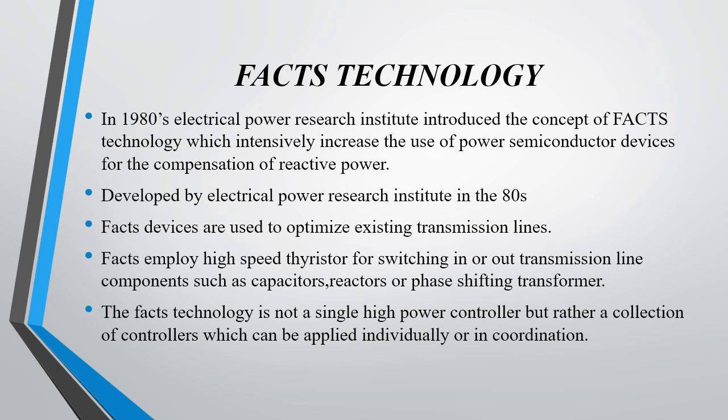Then let's move to FACTS technology. In the 1980s, the Electric Power Research Institute introduced the concept of FACTS technology, which intensively increased the use of power semiconductor devices for the compensation of reactive power. FACTS devices are used to optimize existing transmission lines. And FACTS technology is not a single high power controller, but rather a collection of controllers which can be applied individually or in coordination.